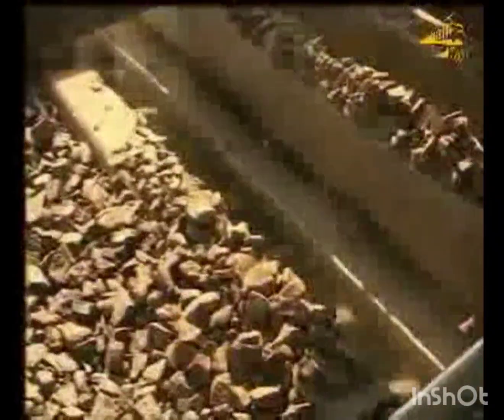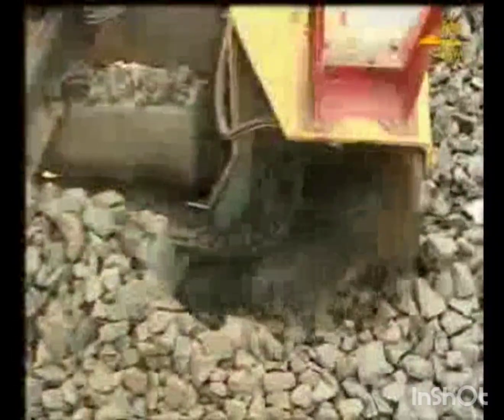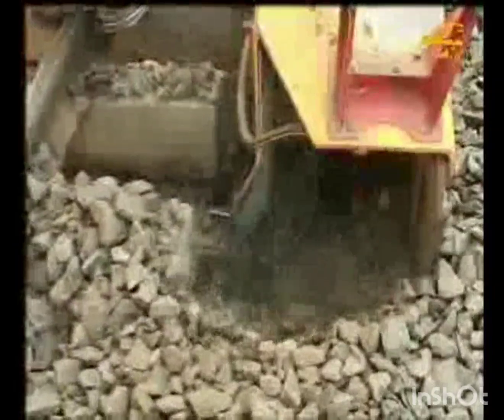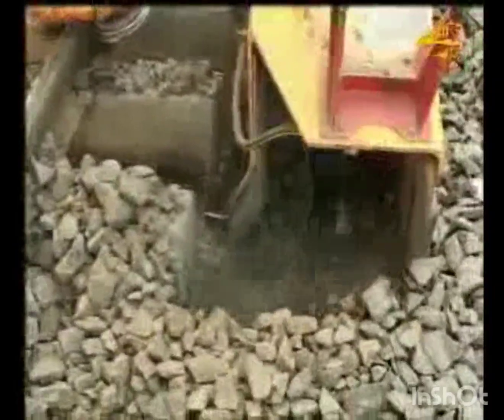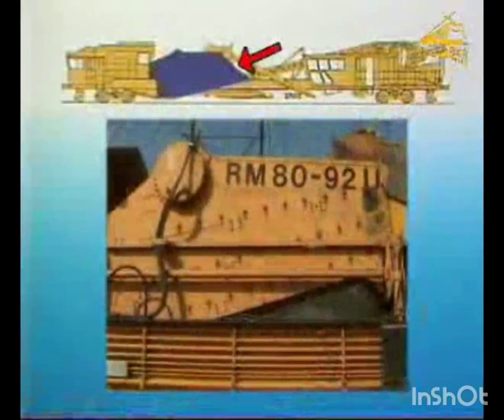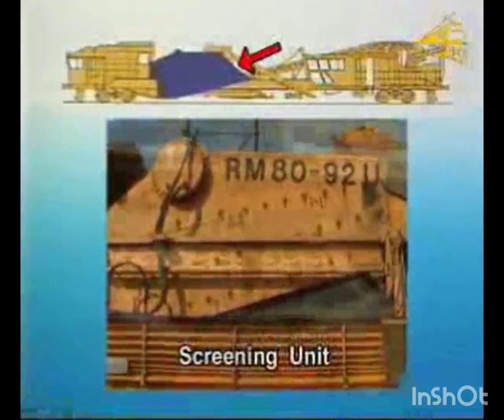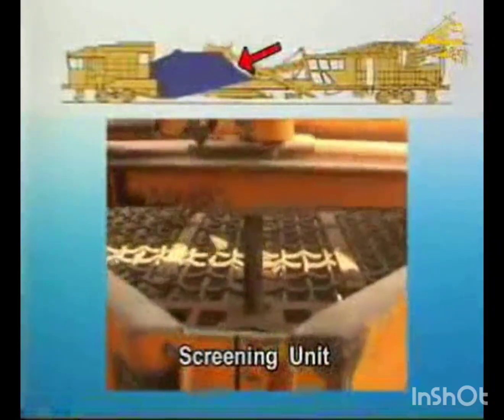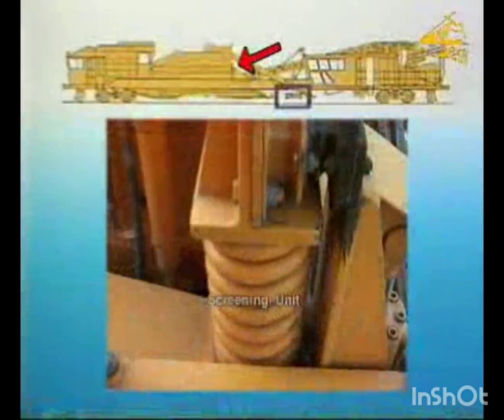Removal of the material from the ballast bed and the action of the chain transferring the material to the screens sufficiently breaks up the excavated material for its proper screening. The free oscillating vibrating screen has a hydraulically powered linear vibrator. The 3-grade screening unit has a total screening surface of 30 square meters.